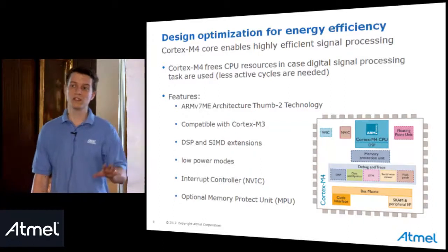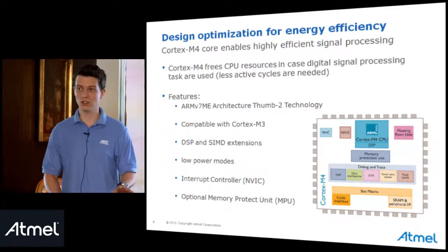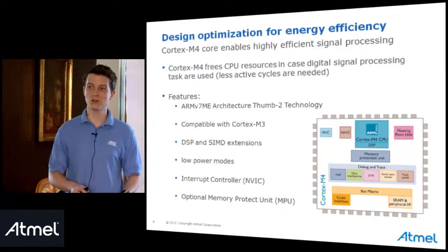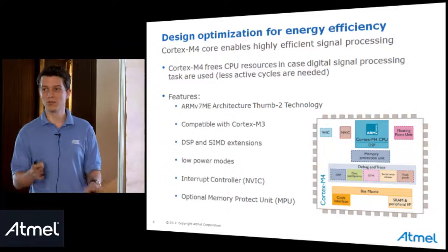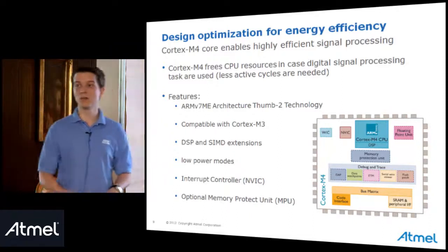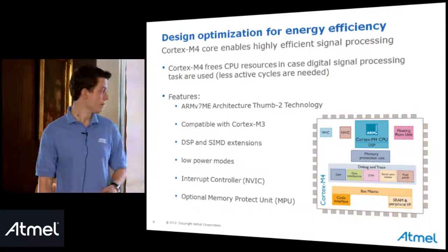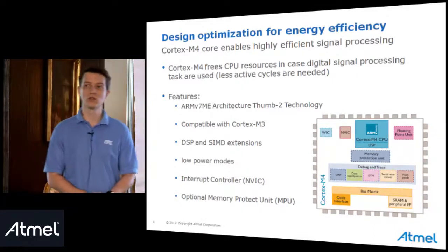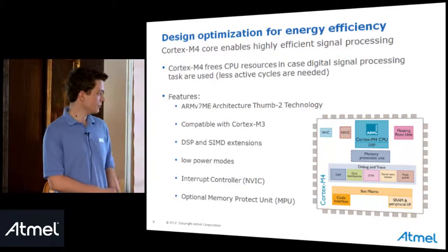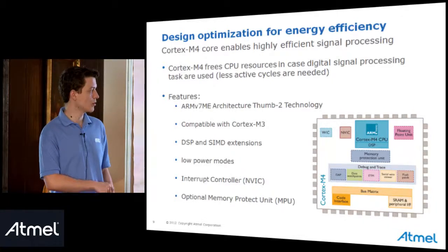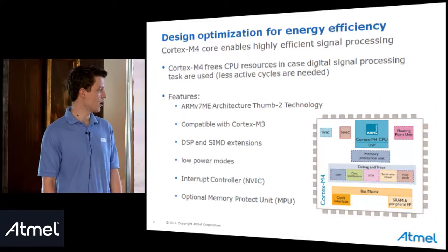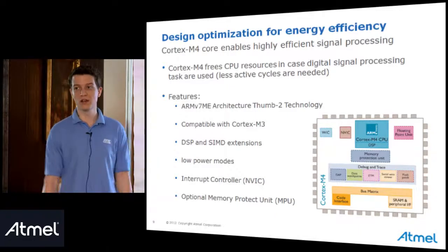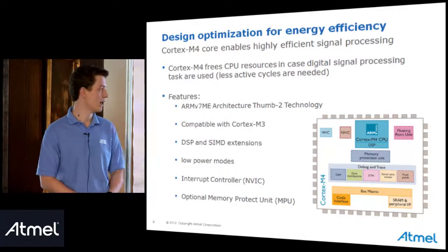So you will have full compatibility between Cortex-M3 instructions and Cortex-M4, but not backward, which means that if you are using DSP or SIMD instructions in your program, you will not be able to run it on Cortex-M3. Okay? We also have the standard low power modes that you can find on Cortex-M products, the nested vectored interrupt controller, which is called the NVIC, and an optional memory protection unit, which is included in the SAM4L.